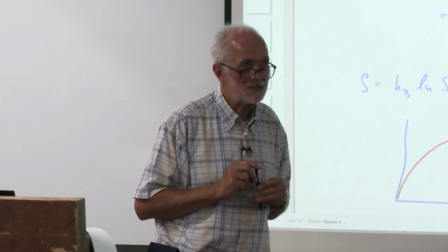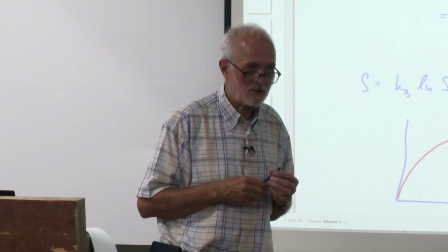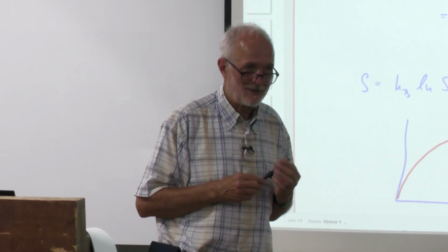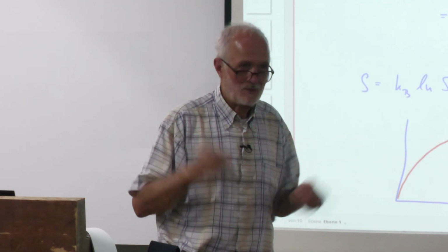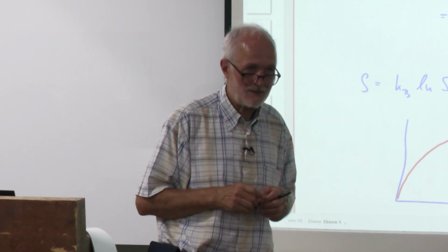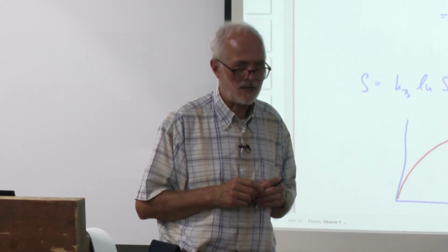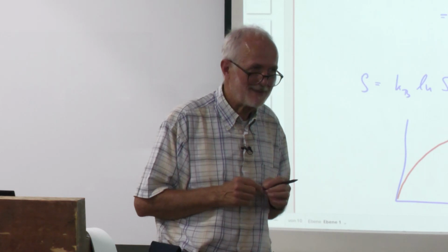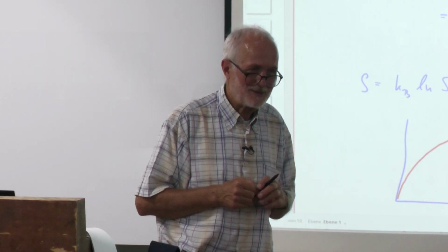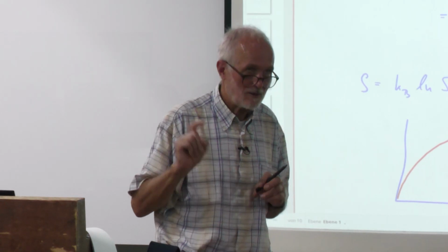There are substances, but this has other reasons, which have much higher concentration of vacancies. And that's technically important. You can go up to 0% of vacancies in certain, I think it's not in metals, but in ionic crystals. One example is zirconium oxide doped with yttrium oxide.